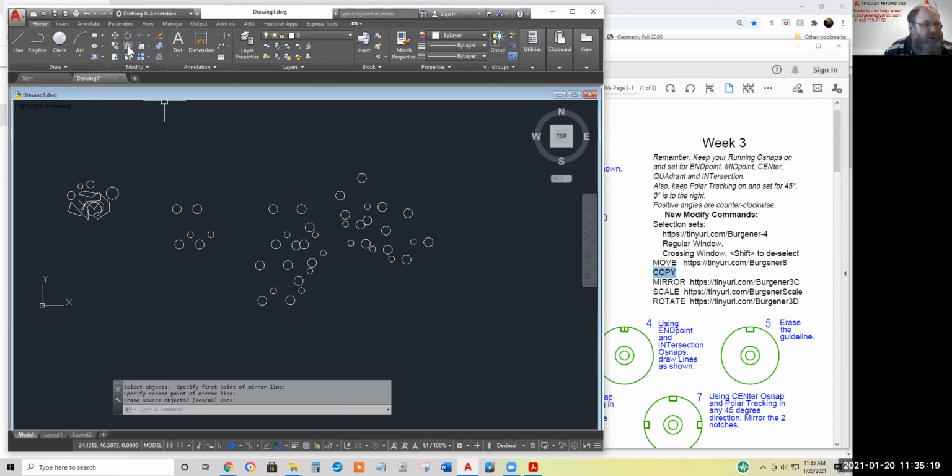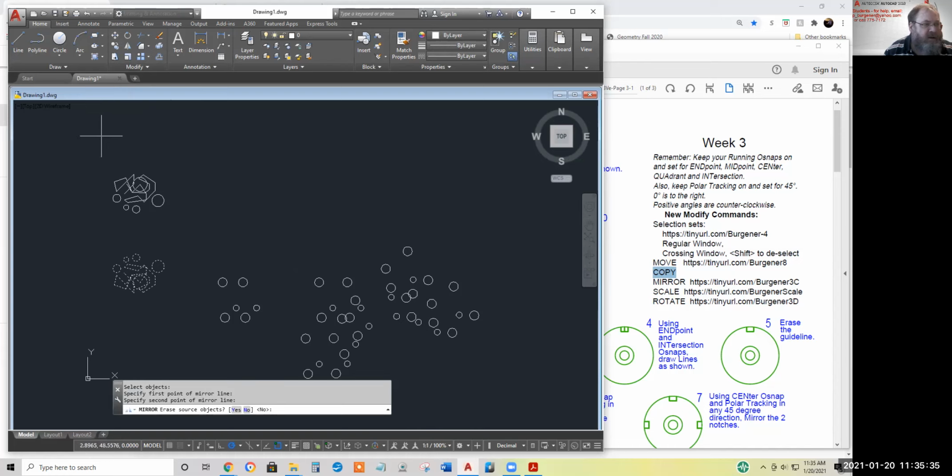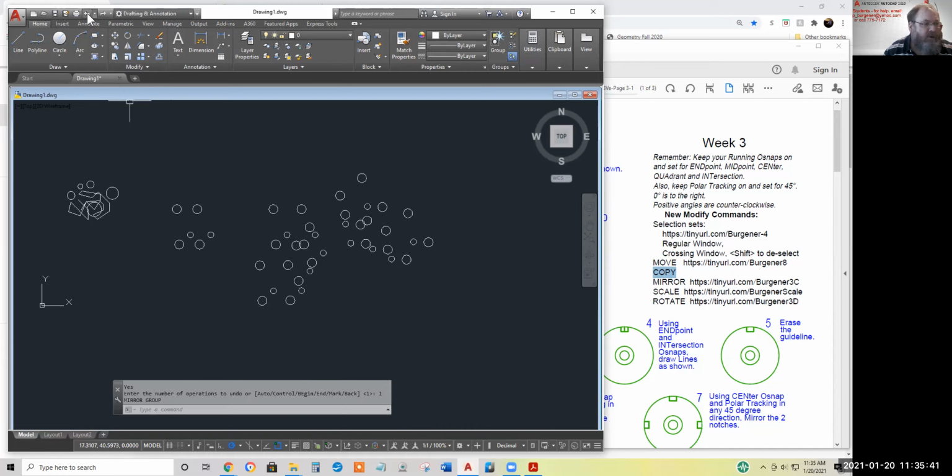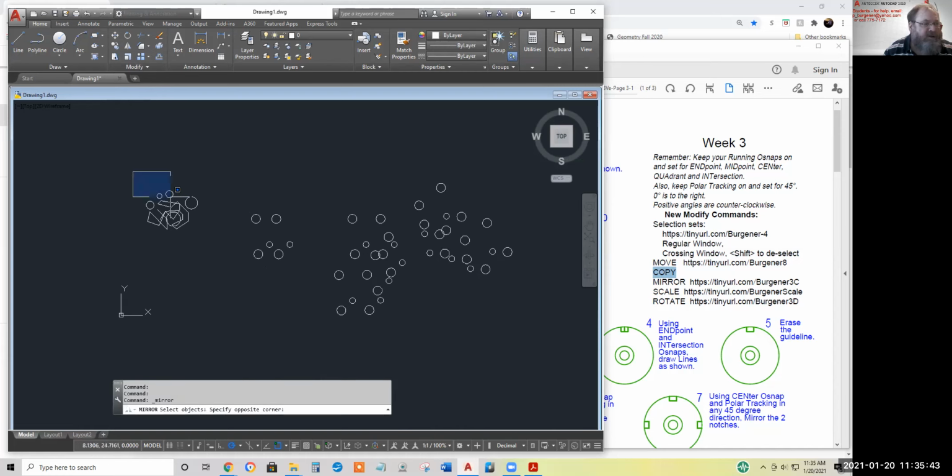In architecture work, floor plan work, quite likely you'll take advantage of polar tracking to make a mirror copy about a horizontal or vertical line. I'll launch mirror command again. Sorry, talking and working at the same time here. Mirror command, select stuff, enter, draw a vertical or horizontal line to make, say, hotel rooms across the middle of the hallway, for example. Hit enter to say yes.